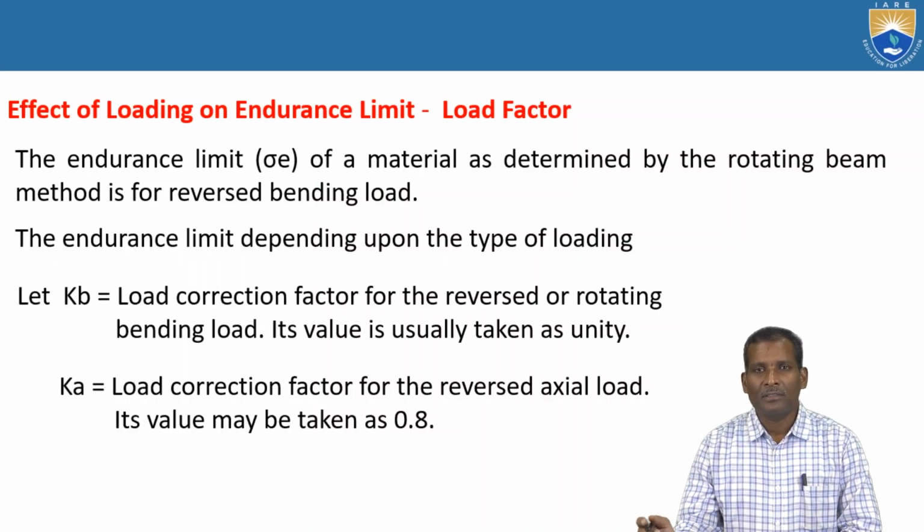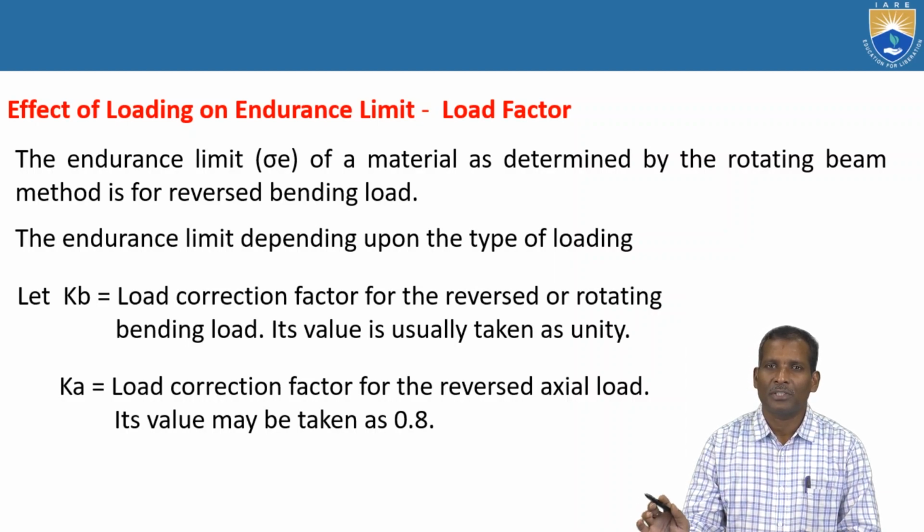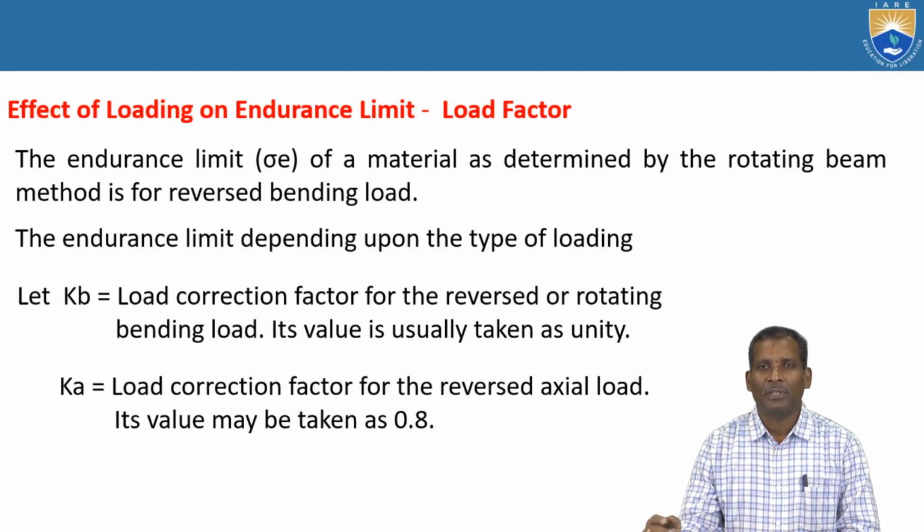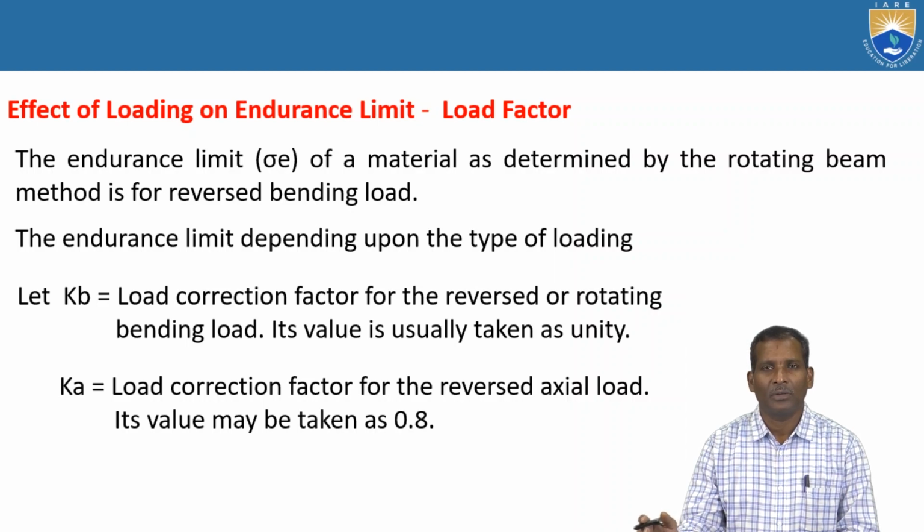So for the effect of loading on endurance limit, we have to take the load factor. How many loads are there and how to take this load factor, I will explain in this session. Actually, the standard specimen is subjected to reversal bending loads. Whatever we have tested under a fatigue test, we have plotted those values on the SN curve. By using that diagram, we will find the fatigue strength of an object for a particular number of cycles.